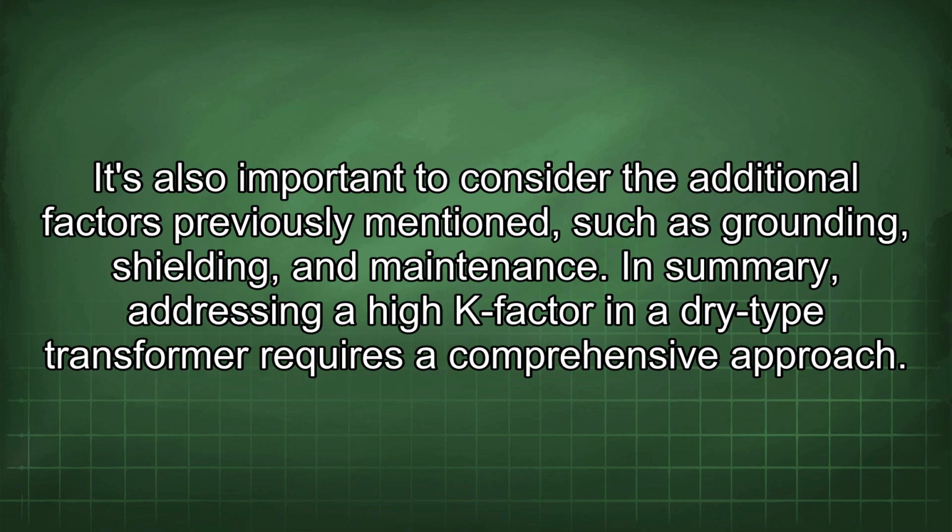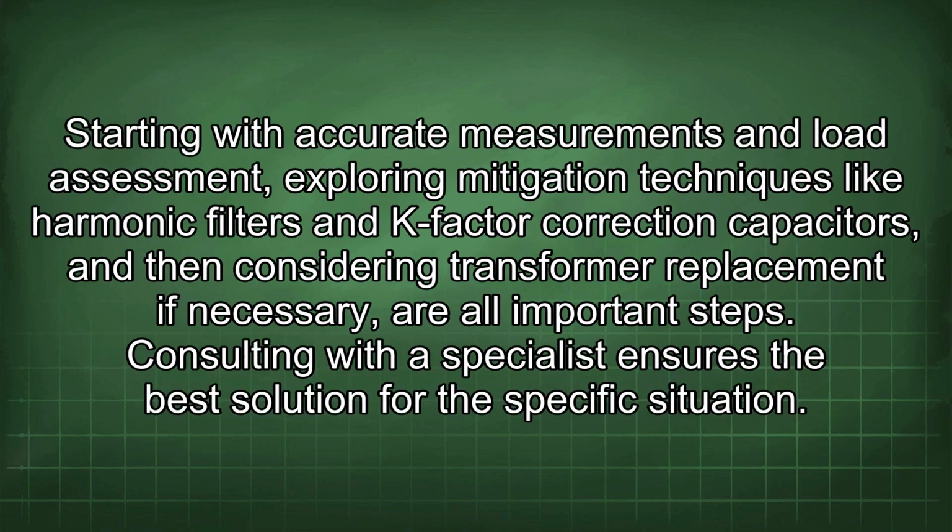In summary, addressing a high K-factor in a dry-type transformer requires a comprehensive approach, starting with accurate measurements and load assessment, exploring mitigation techniques like harmonic filters and K-factor correction capacitors, and then considering transformer replacement if necessary. These are all important steps. Consulting with a specialist ensures the best solution for the specific situation.